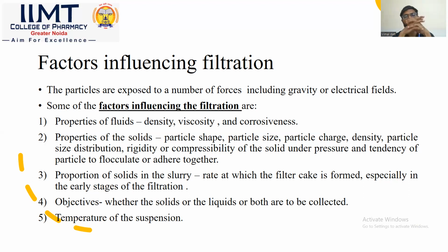Such as properties of fluids. Density: highly dense solid will fast stick on the filter bed, and then viscous fluid. Viscous slurry will take some more time for the filtration, and then particle shape, particles with irregular shapes take more time for the filtration. So these are some basic factors that will influence the rate of filtration.